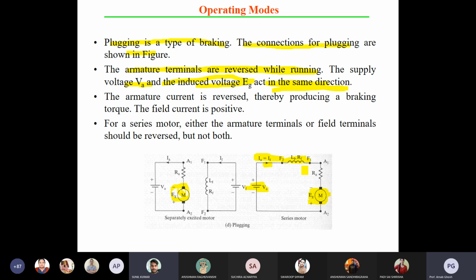First, in the case of a motor, you are giving the supply. After giving the supply, the armature is there, and current is flowing through the armature. So who is the cause? Armature current is the cause for generating that back EMF. Why? The current is flowing through that armature coil or armature conductor, so it can develop some magnetic field.